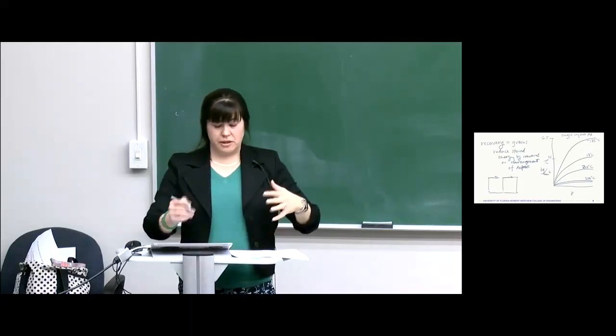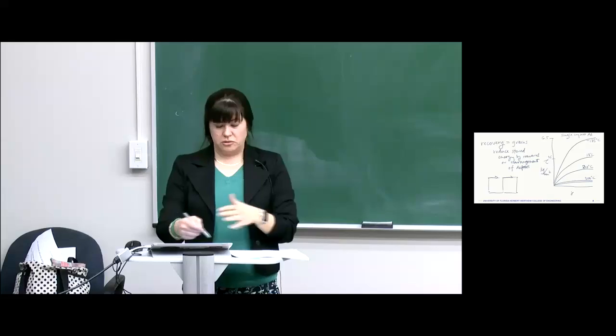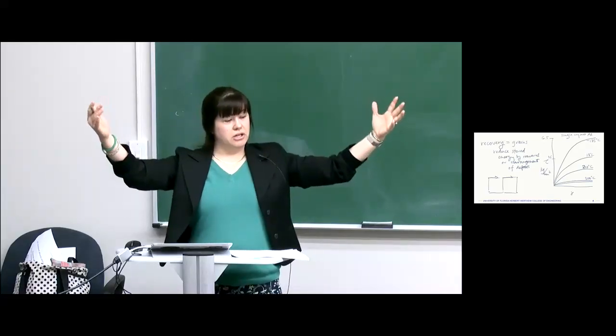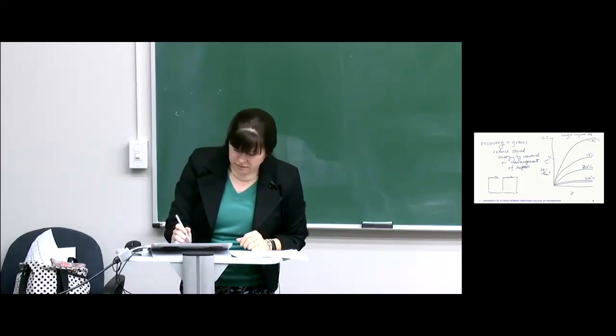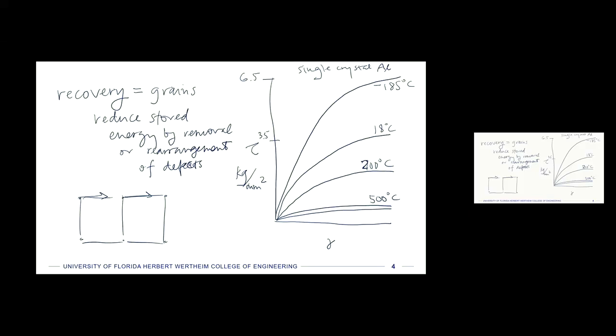So when we do that, if you think about this lattice as not just being these two little unit cells, but being very large, then we're going to introduce sort of these stretches in the lattice, right? So I'm just going to draw it like this, for lack of a better way to do it. So I'm going to draw kind of this picture, where on the top we have 5 planes all vertically aligned, but on the bottom we go down to 4 or 3, right?